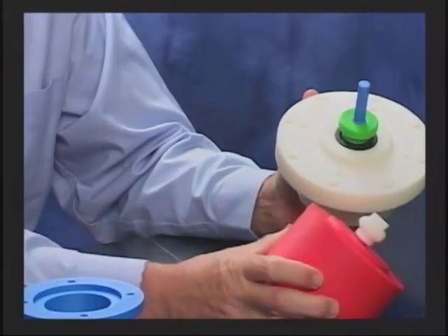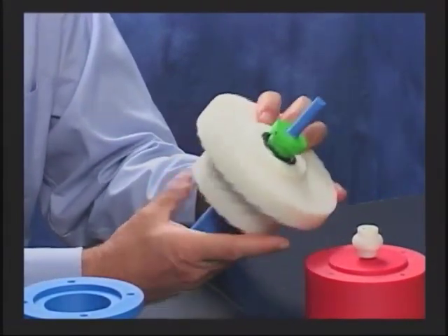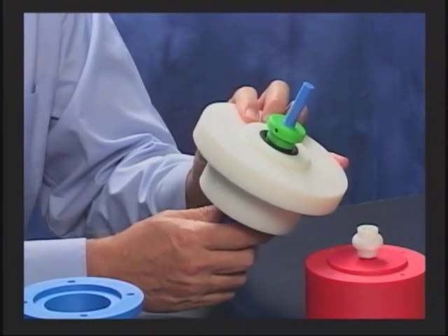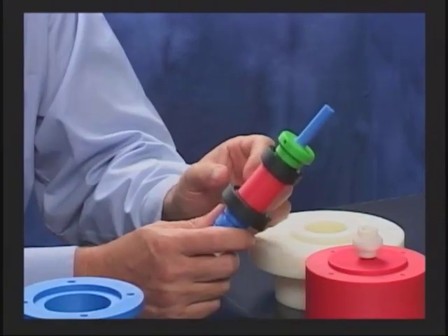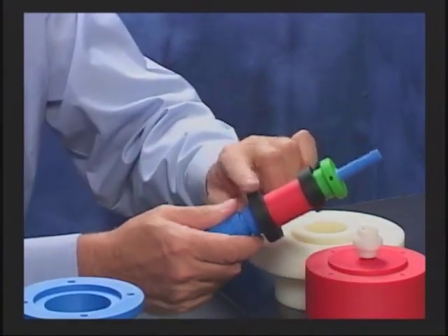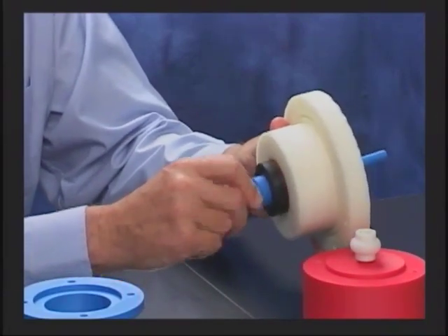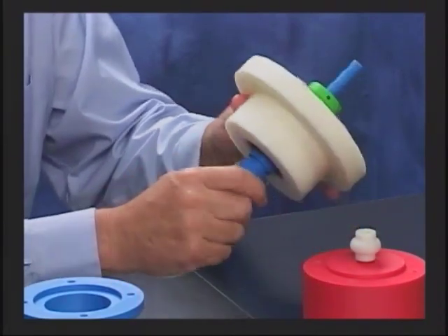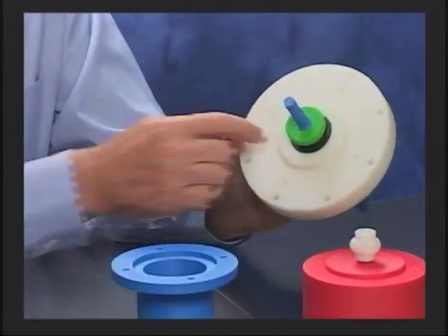But remember, we had a lot of contributing factors there. We had the bearings, and how they fit on the shaft. Then we had another joint where the bearings fit inside of the housing. As you can hear, they rattle around in there a little bit. Then after they went on, we had the adapter that went on, and it had a pilot.